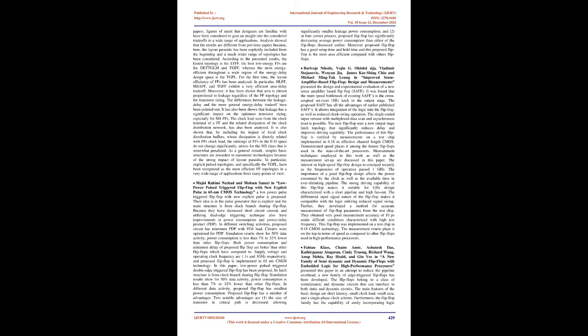Both power consumption and minimum delay of the proposed flip-flop are better than the other flip-flops it was compared to. Supply voltage and operating clock frequency are 1.1 V and 1 GHz respectively, and the proposed flip-flop is implemented in 65 nm CMOS technology. In this paper, a low-power pulse-triggered double-edge triggered flip-flop has been proposed.